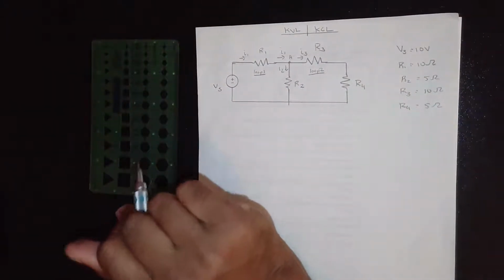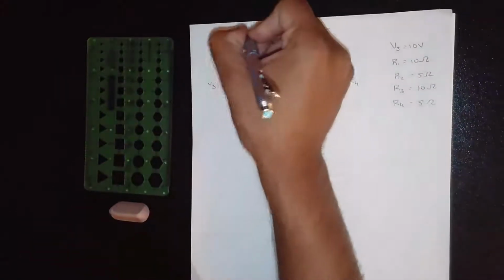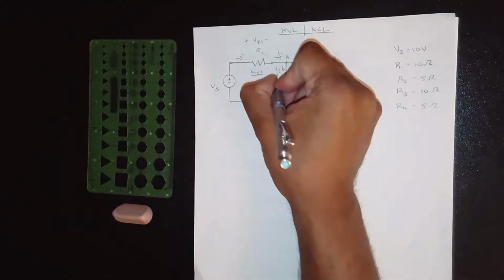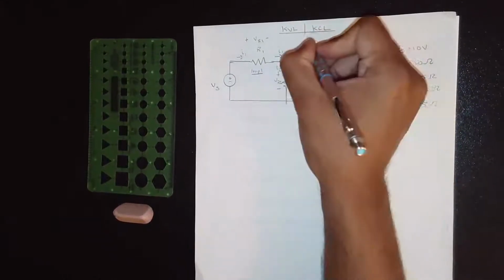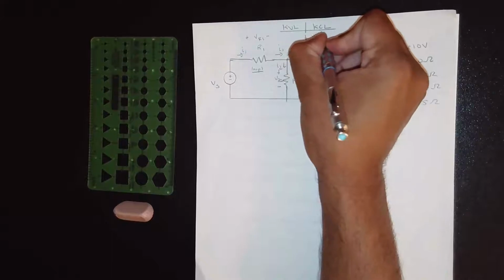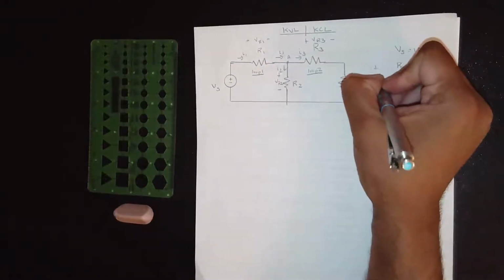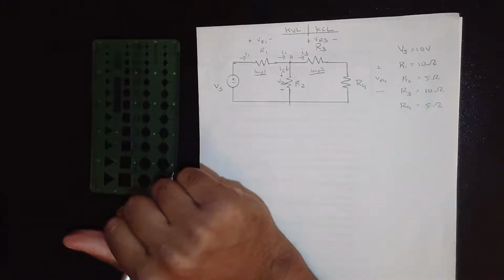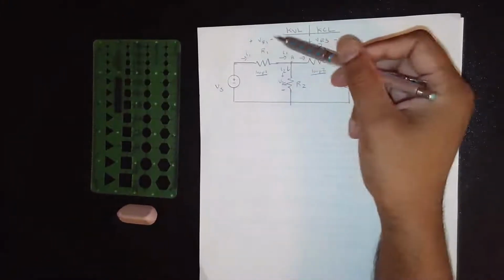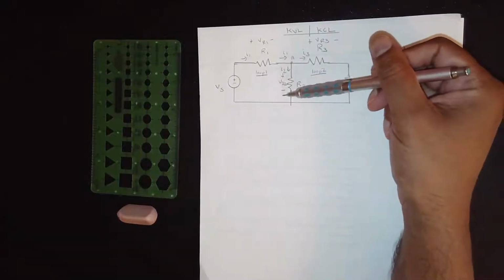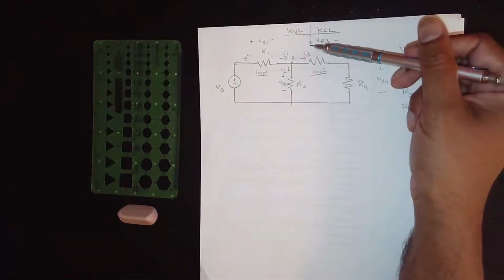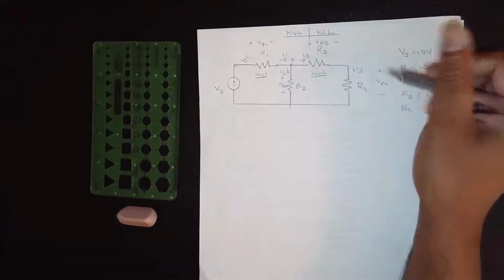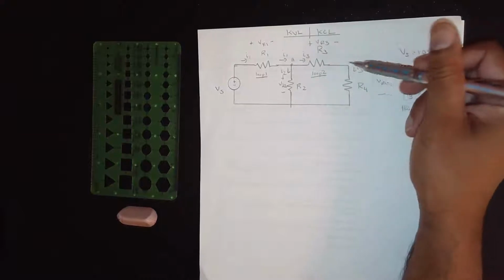And then write out voltages. So when we write out the voltages, this is going to be VR1 here. VR2 here. It's going to be VR3 here. And it's going to be VR4 here. Those are going to be our voltages. Because I1 travels across, it drops down. I2 travels down. It's going to create a VR2. I3 is going across. It's going to create a VR3. And guess what's coming down? I3 is coming down here again, dropping down VR4. Remember, I3 goes from here, here to here.